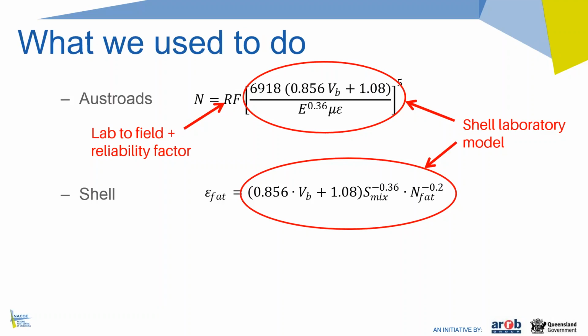And you could argue, based on what's on this slide, that we could replace the mean laboratory performance of 12 mixes tested in the 1970s with the mean laboratory performance of a current Australian mix tested now, and put in our own laboratory model there, as long as the testing that we're doing is similar, or the test configuration is similar to what Shell used to develop their general model for 12 mixes.